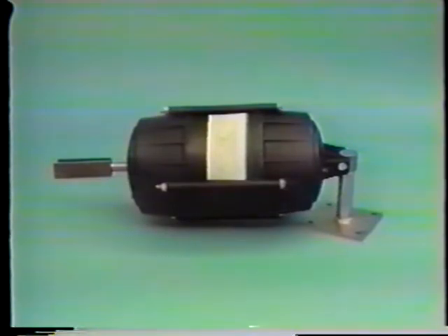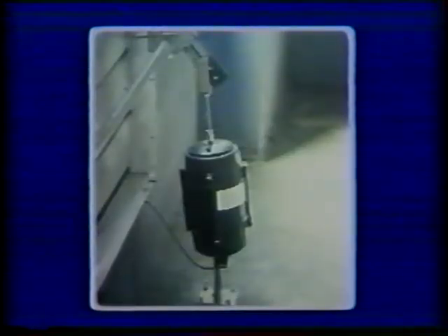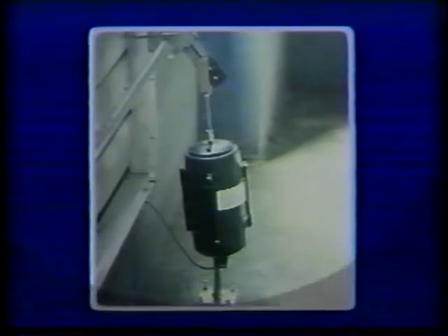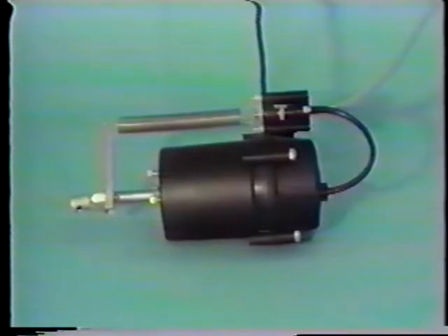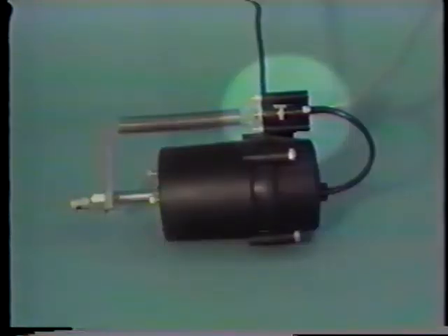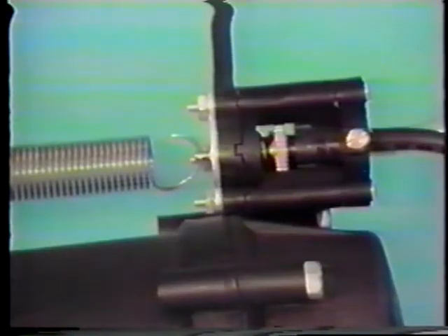The post mount actuator is attached to the mounting bracket with a post assembly and is free to swivel on that post. In this application, the actuator is connected directly to the crank arm rather than using linkage. Here is a 3-inch actuator, the 2473 series, with a positive positioner attached to it. A positive positioner is used to properly sequence single, or in some cases, multiple damper actuators within the control sequence. The positioner is used where the position of the damper is critical to system operation.